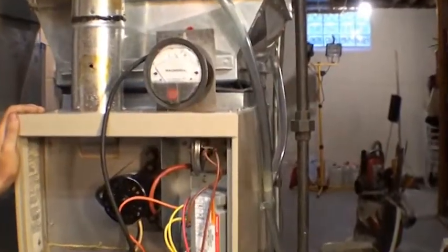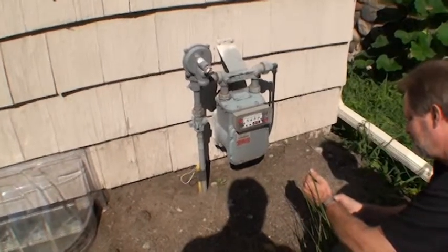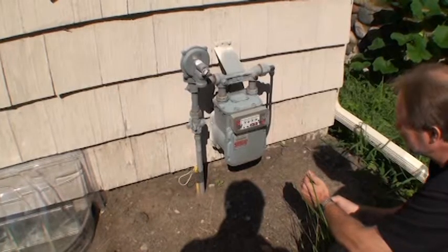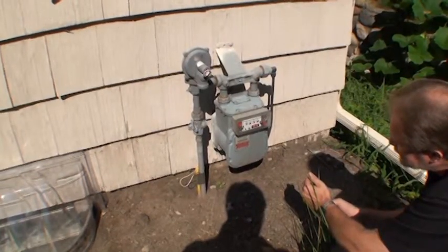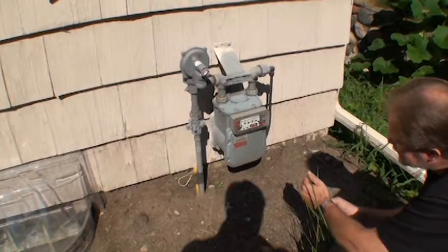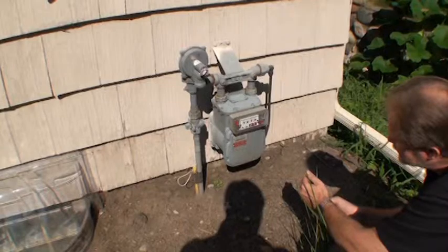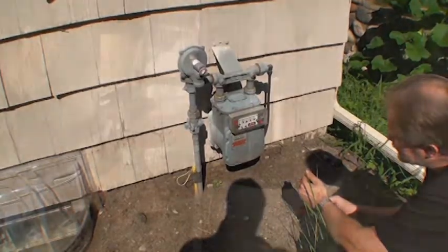Check gas pressure at the furnace gas valve. Clock the gas meter. The clocked BTUs need to be plus or minus 2% of the furnace data plate input. In some situations, this is not possible, and you will need to document the reason. To clock the meter, you need to time the revolution of the half cubic foot dial and calculate the BTU input by dividing 1,800 by the seconds clocked.